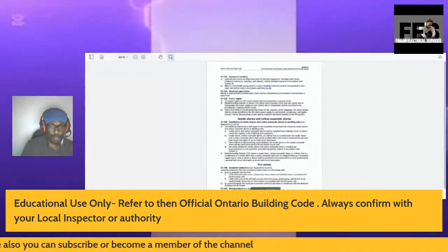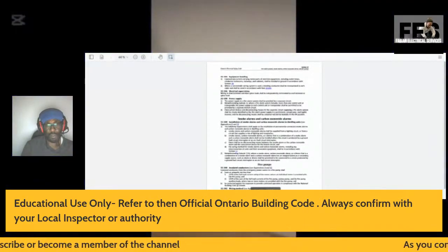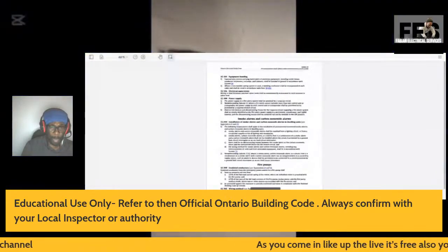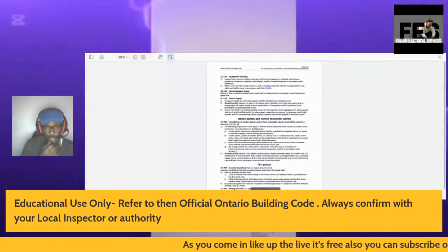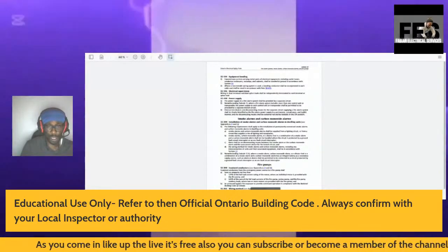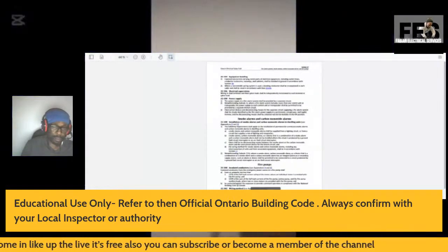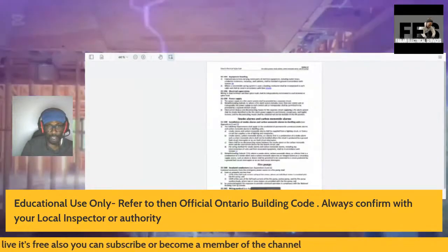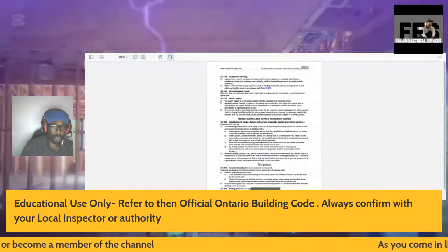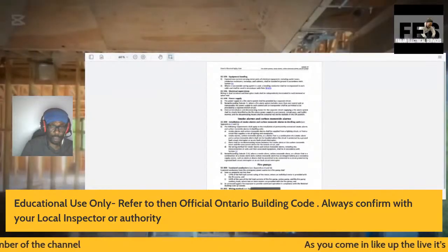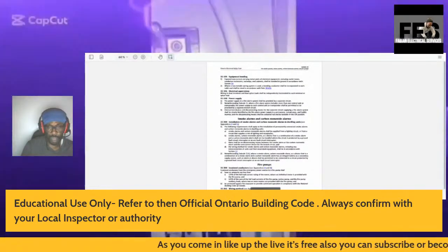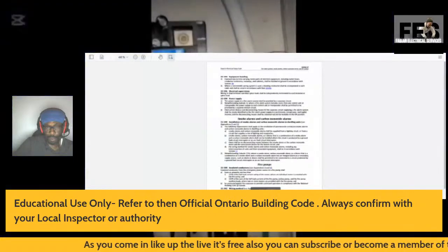If your battery is working, it will signal. Also, make sure that your smoke alarm is not expired. Max 7 years for the normal smoke detectors and 10 years for the other kind of strobe-like smoke detectors.